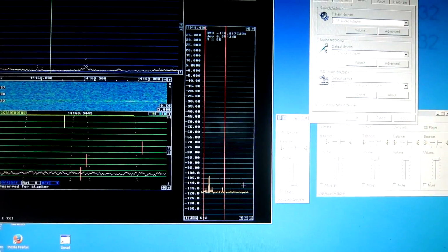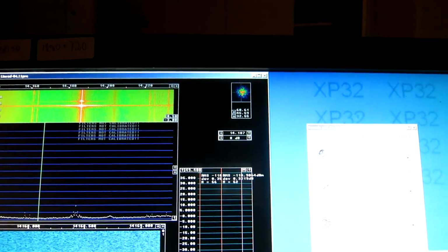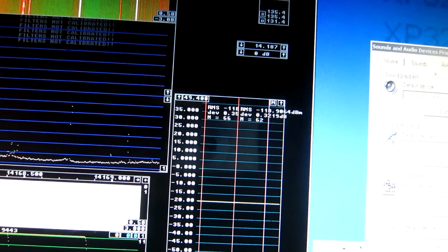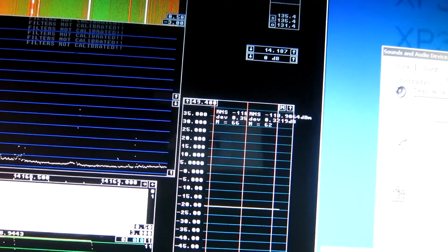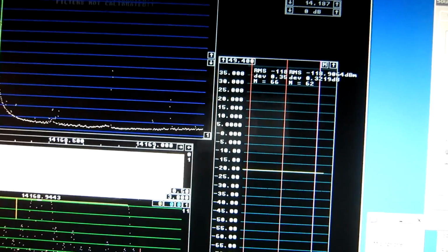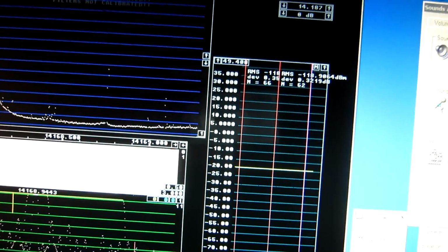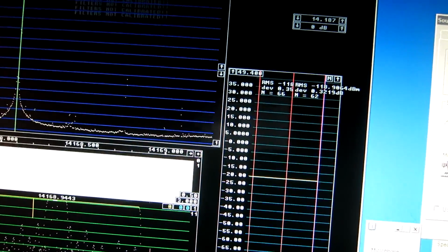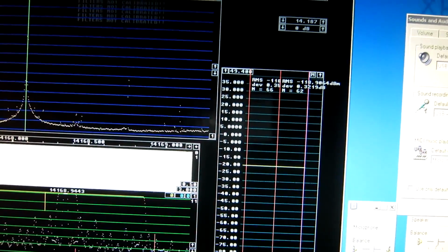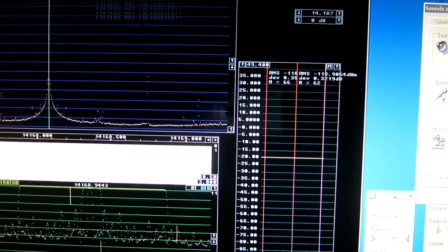And with the capacitor, the noise floor I see is minus 118.9. This is not very good. Saturation at minus 21. That is 3 dB earlier than the Softrock itself. And a noise floor of minus 119, rounded. That is about 5 dB worse than what we get with the Delta 44. There are other cheap sound cards that do better than this one.